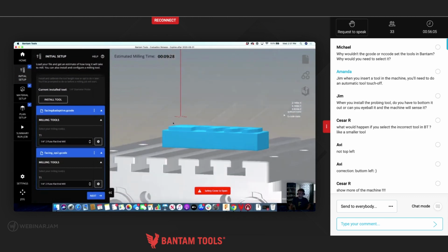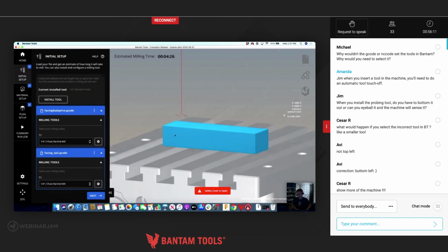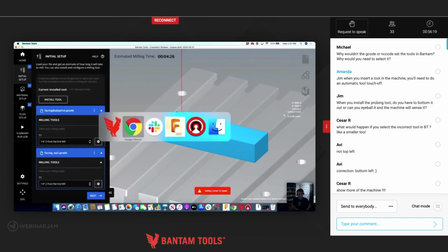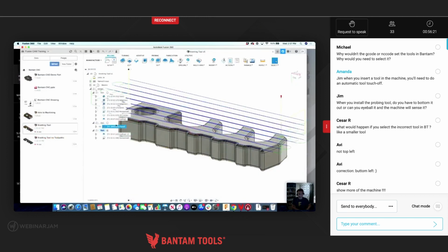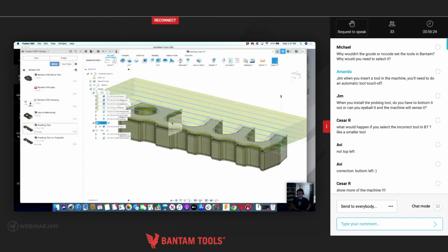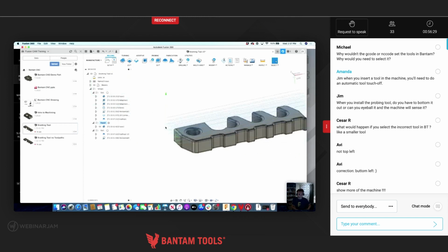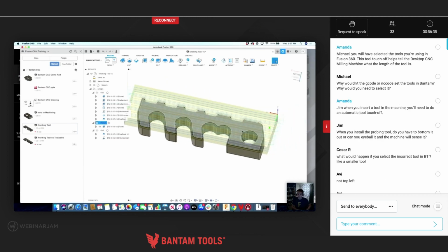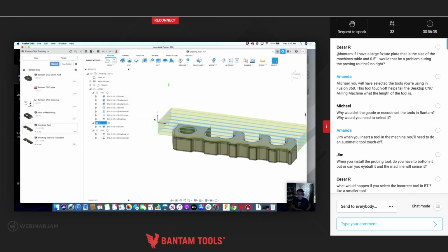Now we're seeing a little bit different of a thing. Let me go ahead and hide this first facing. And so to set up this op, I would do the exact same thing that I did before, because in Fusion, if I switch over here for op 2, we are still aligning with this top left surface. So I would go through the same automatic stock location routine,